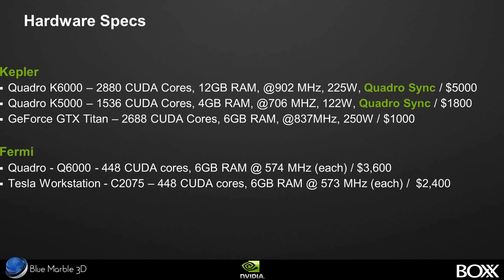The Quadro K5000 that everybody's used to, this is another thing that we were hoping to do this webinar sooner, but this is about the earliest we can get to it with all the specs and having everything. A lot of people jumped from the Quadro 6000 to the Quadro K5000. Well, it's not an apples-to-apples comparison because the K5000 is using the smaller chip. The Quadro 6000's big brother in the Kepler is the K6000, which is not out yet. So Fermi cards versus Kepler.